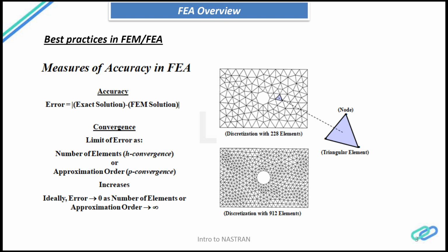One of the things is to discretize the domain into finer elements, then choosing the right element that comes next, and choosing what order of elements for what kind of analysis, and then choosing the loads, boundary conditions, materials, and so forth.